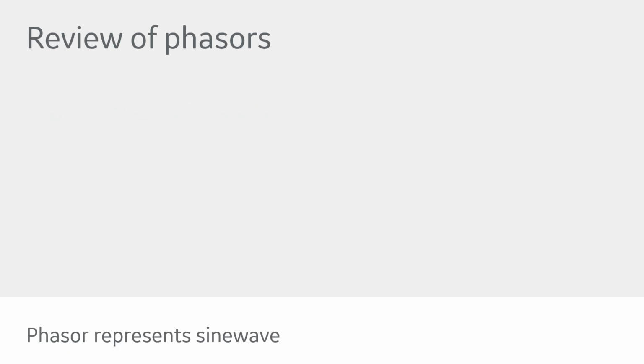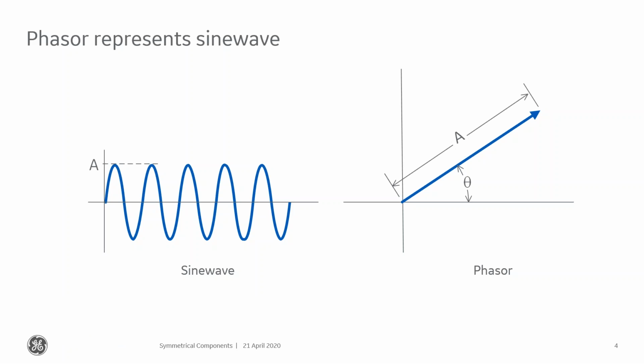Now, when I set an overcurrent element in a microprocessor-based relay, usually I set a pickup value. And that pickup value in our relays is in per unit, in per unit of CT. So I'm really translating this into some quantity. If it's a 2000:5 CT, and I set that at 1, that means it's picking up at 2,000 amps, right? But what really is 2,000 amps? Well, I kind of think of that as the RMS quantity, but it could be the phasor quantity.